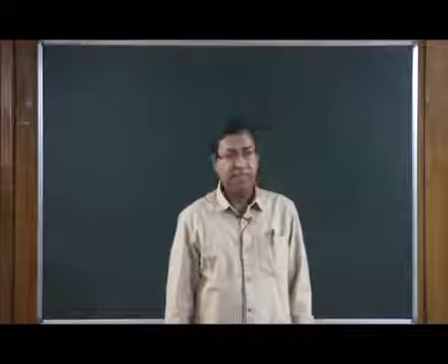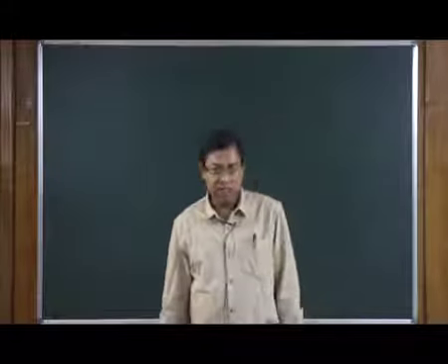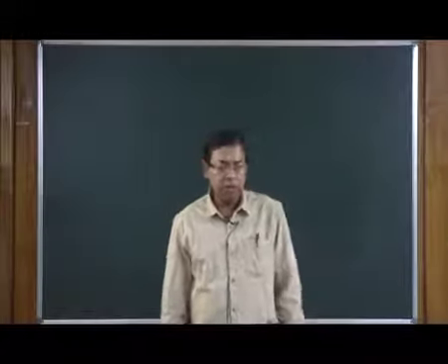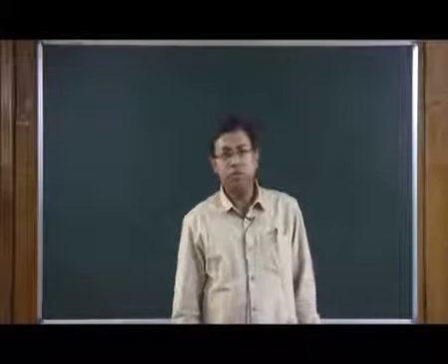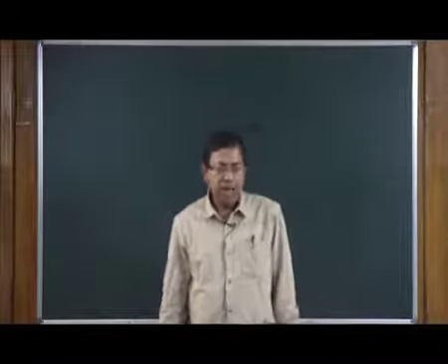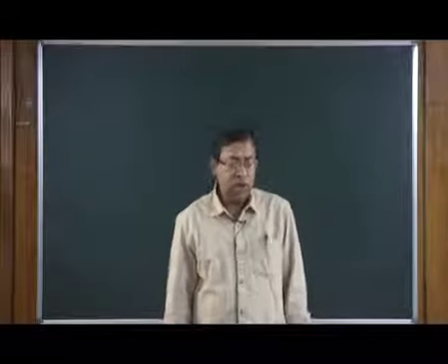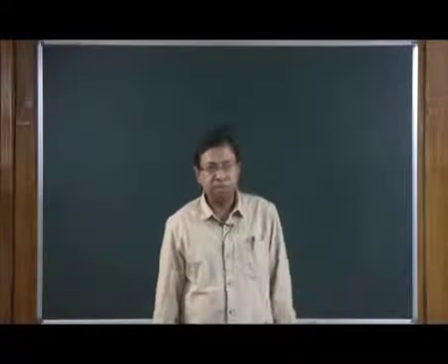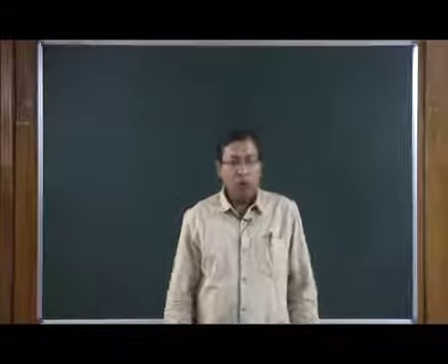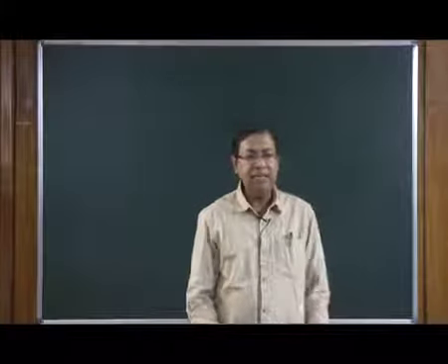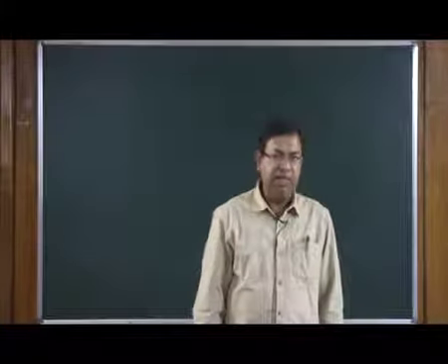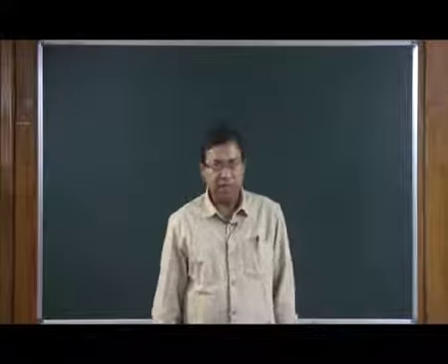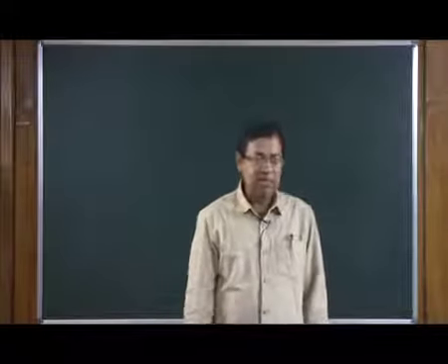In fact, they may not deform at all, which I will give an example of, or the deformation caused could be partially recoverable or reversible when the load or the force applied is being removed. However, the materials which are permanently deformed even when the load is removed are called plastic materials. So, what I wish to state is that all plastic materials are inelastic materials, while all inelastic materials are not plastic materials. Let me elaborate this statement a little more.